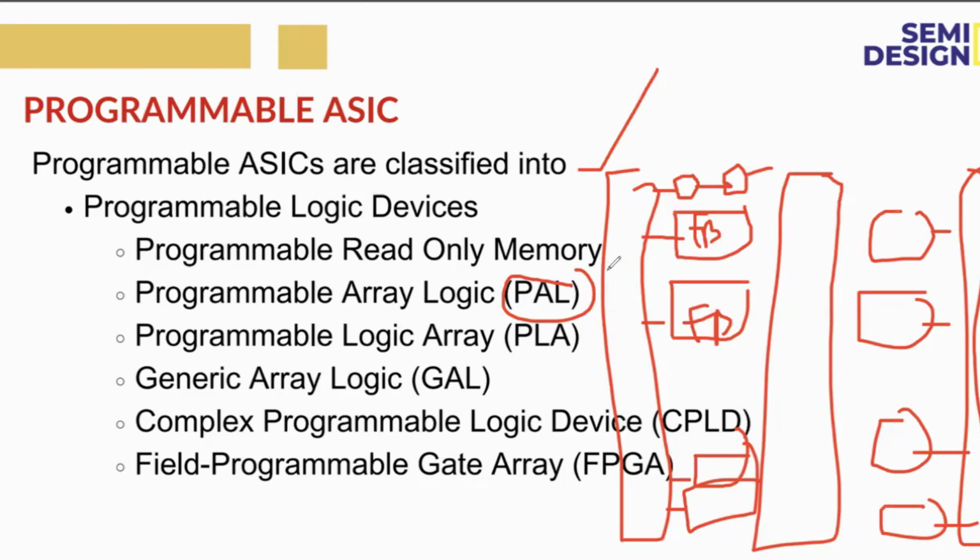The entire device consists of nearly thousands of gates. Therefore, for complex designs, beyond a single PLD, CPLDs will be implemented. What is a PLD? PLD means only this separate block. But with multiple functional blocks, there will be multiple AND-OR arrays. So for the implementation of complex designs, we go to the CPLD.